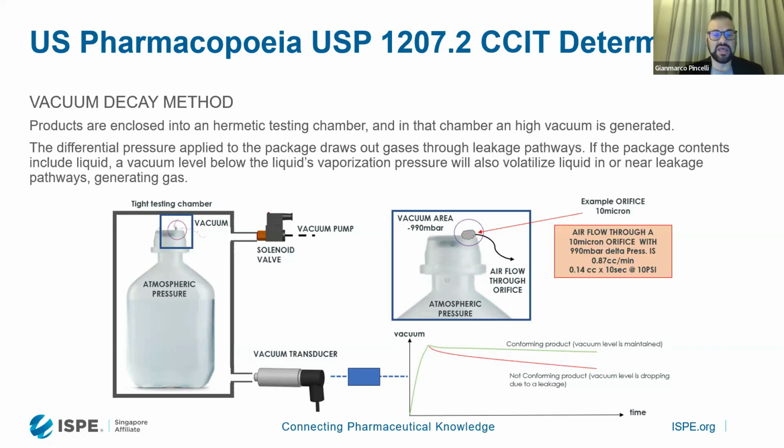It's important to understand, when we are thinking about differential pressure technology like vacuum decay and pressure decay, that the machine is detecting a certain leakage in terms of orifice diameter, but more technically, the machine is looking for an airflow, because the vacuum is decaying due to the airflow and not due to a certain hole diameter. In an indirect way, yes, there is a correlation between the airflow and the hole diameter, which is also affected by the thickness of the walls of the container.